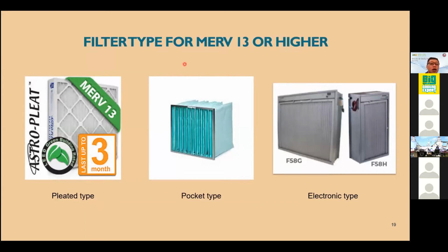So option one is the split filter, which I think should be cheap, but not that cheap as well, and it lasts you maybe up to 3 months. Over here it is also stated, I Googled it, and then I cropped and shared. And then you have a pocket filter, which has the disadvantage that the depth is too thick and the static pressure is too high.